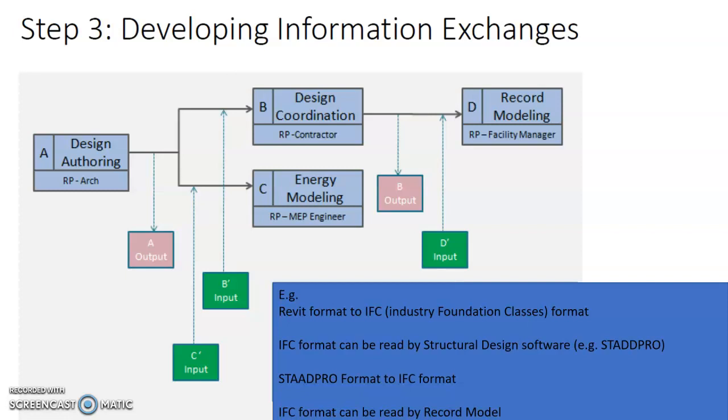They then need to figure out how to do a conversion. You can try to find a macro or an app to convert the information into the .ifc extension. If you cannot, then perhaps we do not use that particular software platform for that particular BIM use. That is very critical.